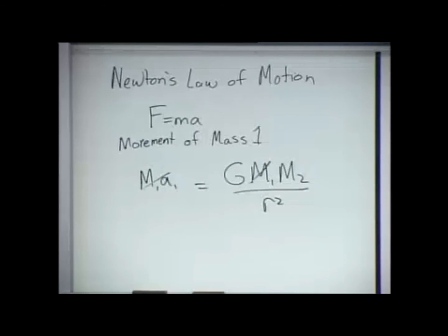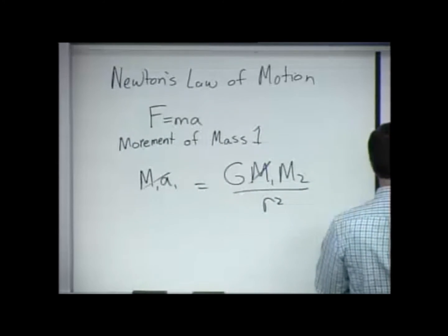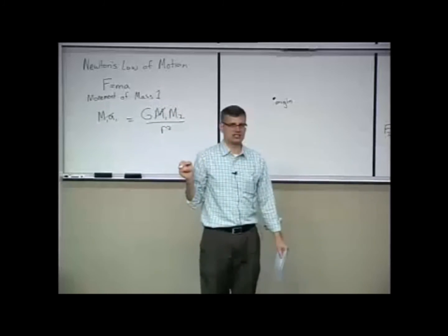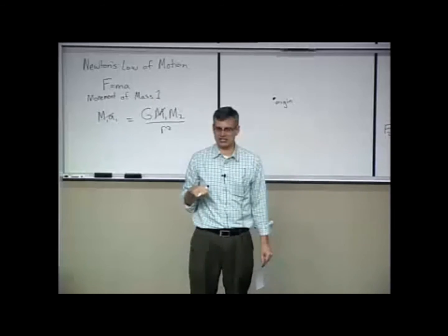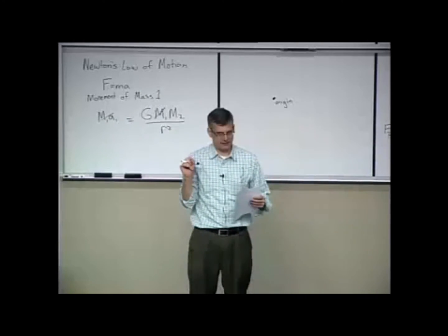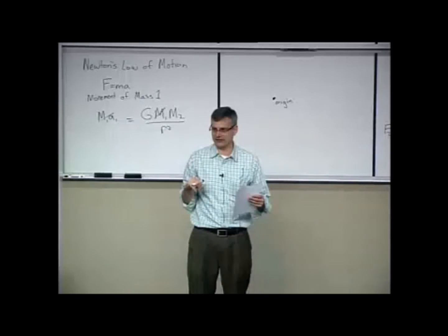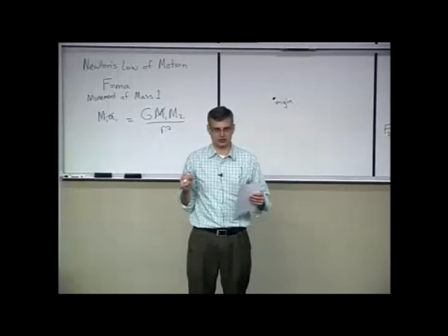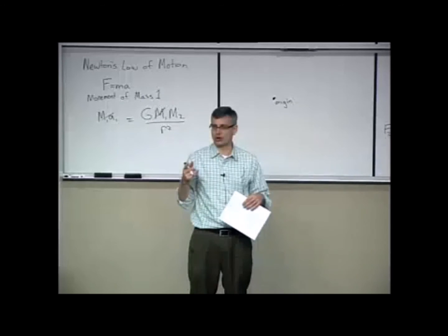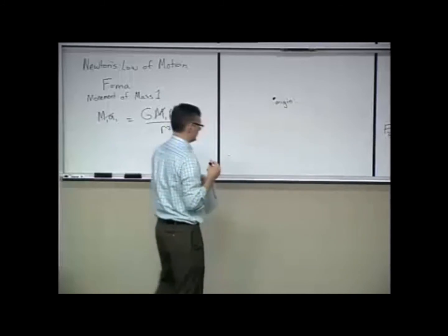Now, we're engineers, so we have to do this rigorously. I've drawn everything as scalars at this point. To really understand orbital mechanics, we're going to have to move into a vector representation. And so here's the convention that we're going to use to talk about orbits in this class. We're going to have an origin. And it is more convenient at this point to work in the cylindrical coordinate system instead of the Cartesian coordinate system. So instead of describing an orbit in terms of x and y, I'm going to use r and theta. And that is actually the physics and mathematics convention, not the electrical engineering convention, because most of this stuff comes out of physics and mathematics books. Electrical engineers haven't written that much about orbital mechanics. If we were doing the cylindrical coordinate system, it would be what? Rho and phi. That's how electromagnetics engineers talk about these things.